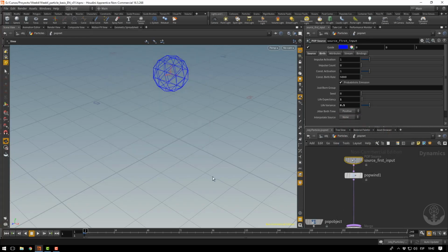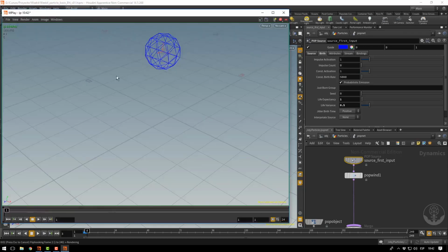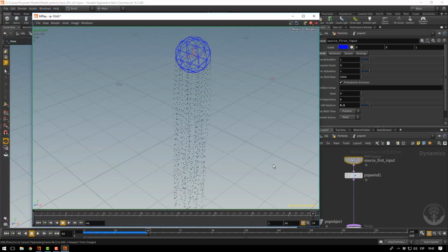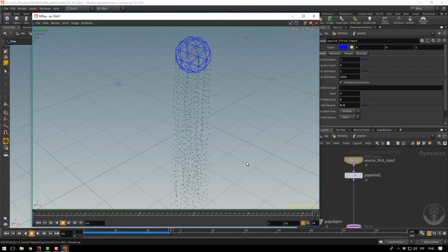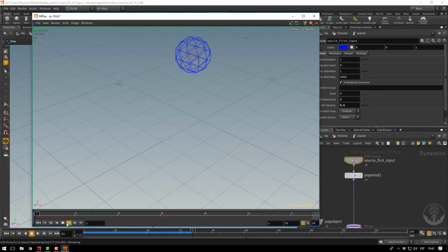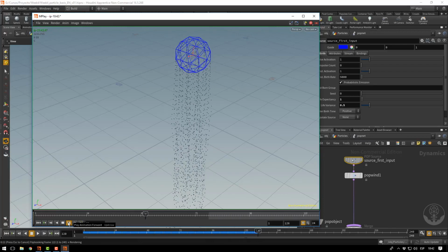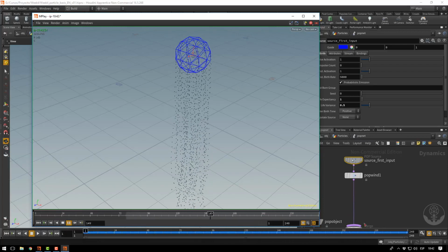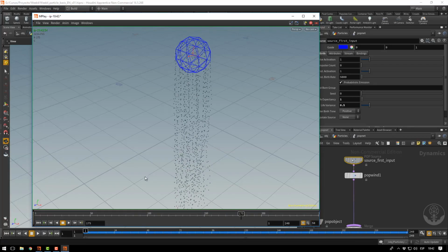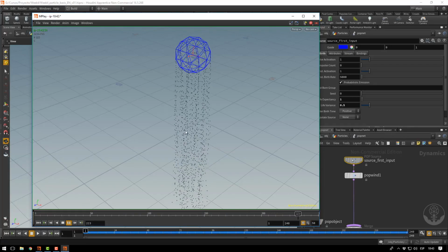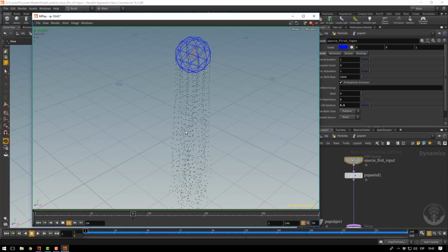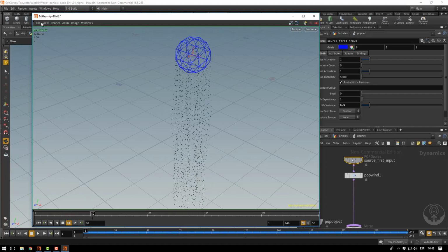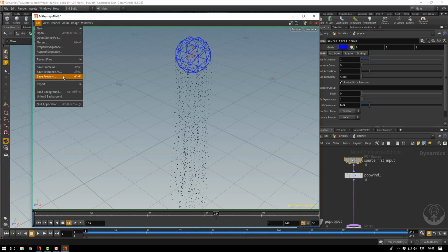So if you click start, a new window will pop up, will load your cache, and you can play it also in real time. And you can set up the frames per second if you want to modify. It's a nice player. It works really very good, and then you can probably save your sequence.